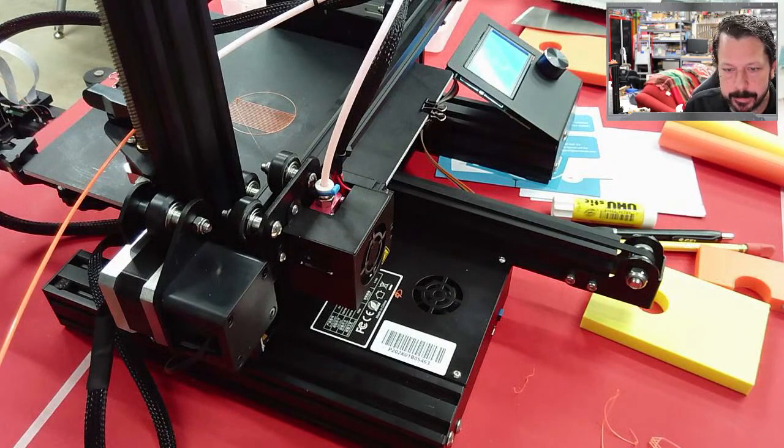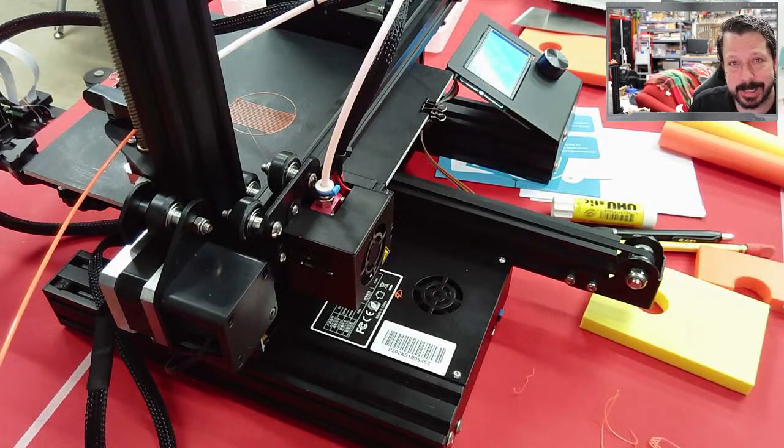But we will dig into G-code here and there, because it is useful for finding things when your machine's doing something that just doesn't make sense, or maybe you've got a particular thing that you want to do, and slicing doesn't do that. It's actually simpler to write the code that you want exactly, or maybe a combination. You've sliced something and then you want particular things to happen during the print. You can go in and edit the G-code, like I said, in Notepad or something similar. It does need to be a text editor that doesn't add things to it.